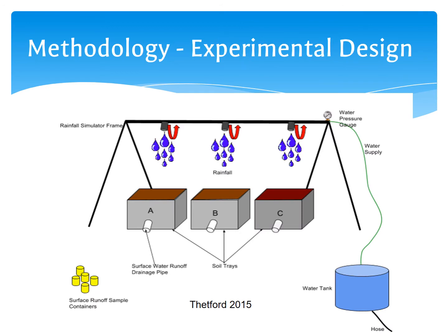Initially, we set up 3 replicates for each of the 2 experiments. Approximately 30 litres of river sand was filled into the non-porous metal tub, which was then filled to capacity with the given soil. Soils were compacted with shovels and wooden blocks to promote runoff and erosion instead of infiltration within the soil. These tubs had a surface area of approximately 0.55 metres squared.